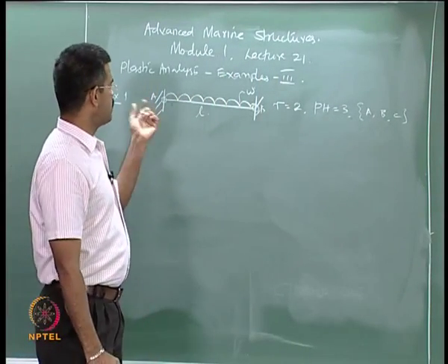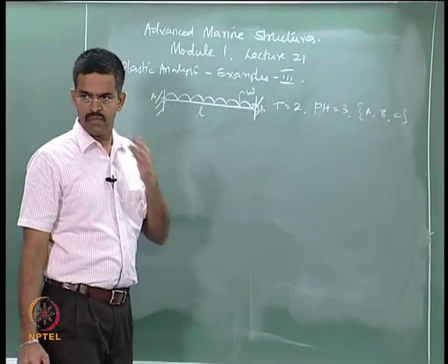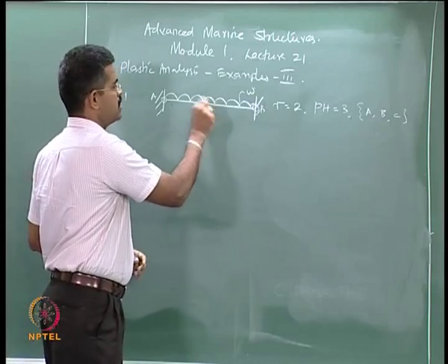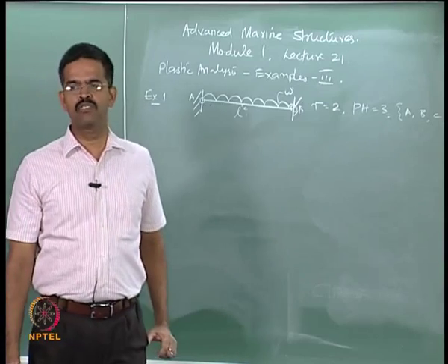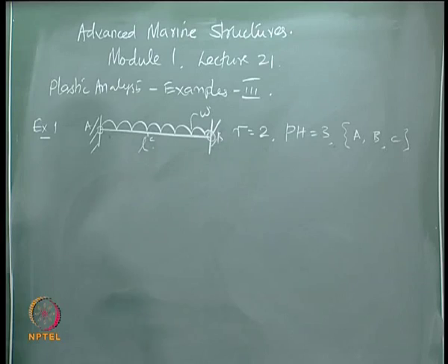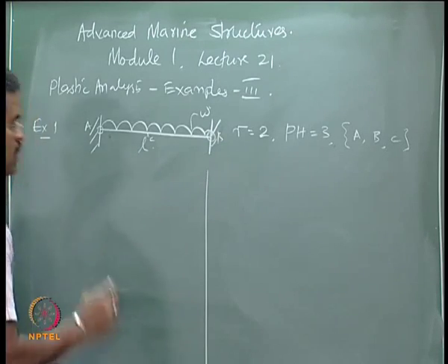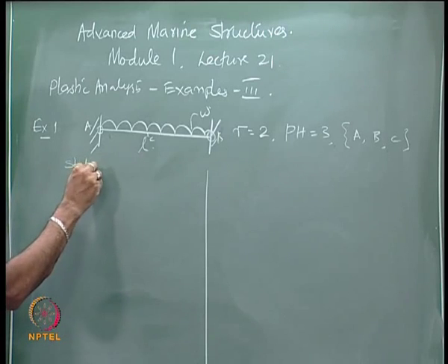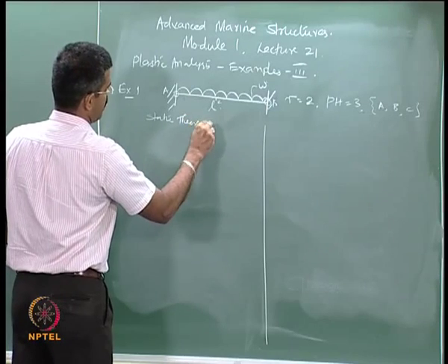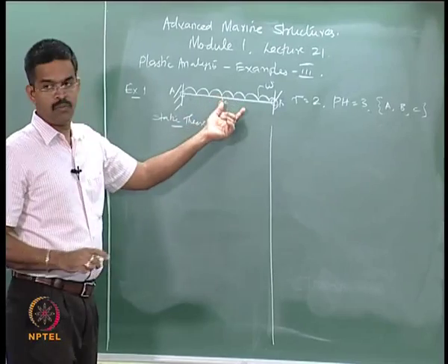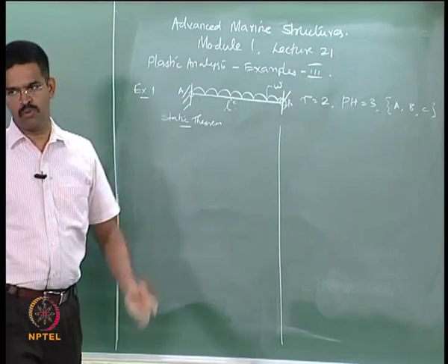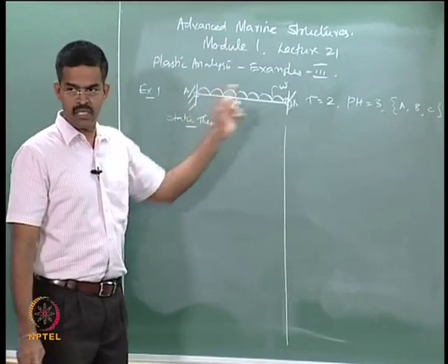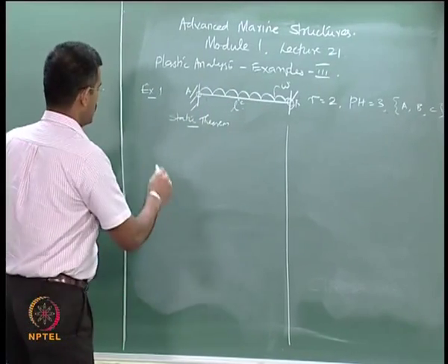Can you guess where the bending moment will be maximum in this given beam? Center. So, I can mark a point C here and say that is going to be the possible point where my plastic hinge could form. Okay. Let us solve this using both the methods. Let us say using the static theorem. Static theorem wants the structure to be in position, it wants the loading to be applied, and now it wants a bending moment distribution for both external forces and internal reactions. So, let us draw the beam.